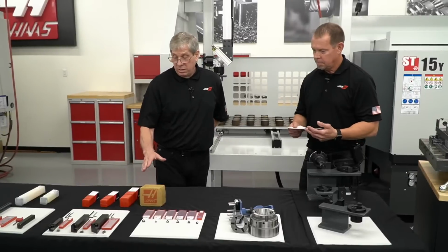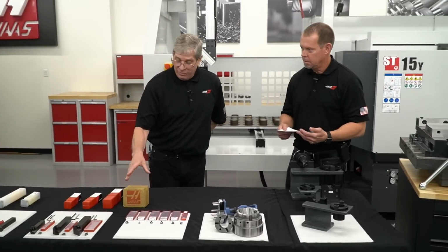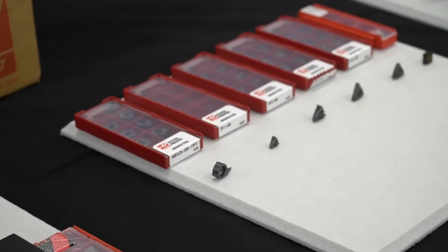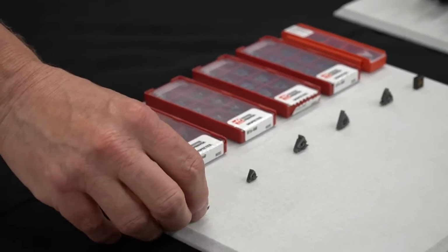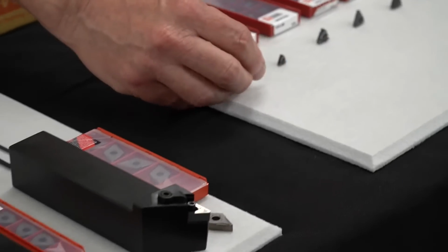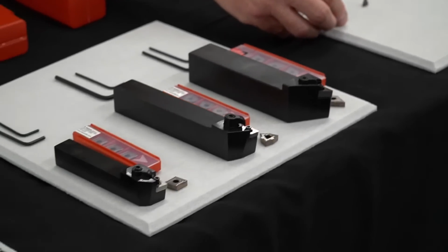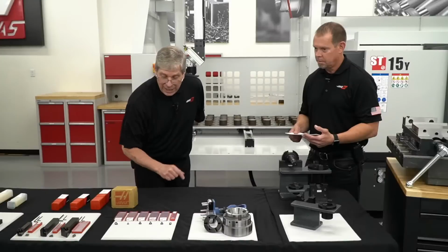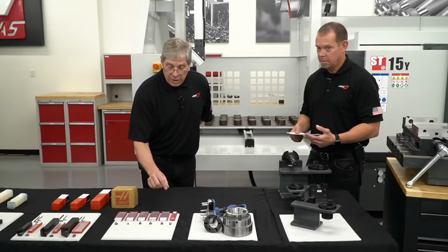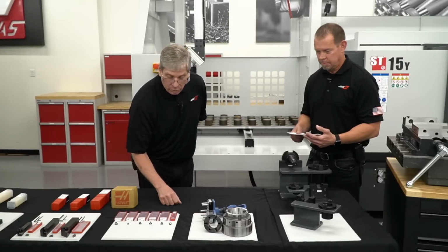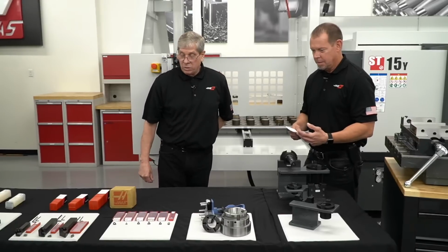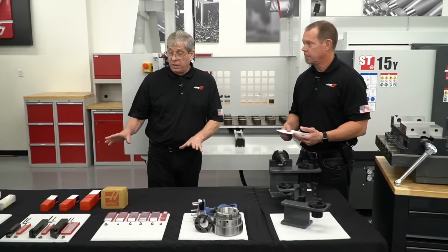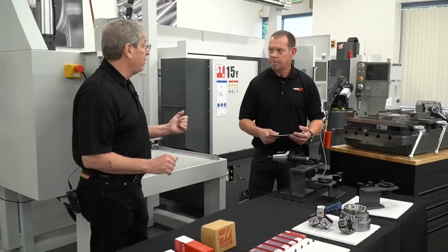On the next placard here, we've got a variety of different inserts that are coming. This is an ID grooving insert that'll screw onto the end of a bar, and then a couple of different sizes and styles of lay-down threading inserts, and then a CNMG boring bar insert there on the end. So just a variety of lathe tools that's coming in the very near future.